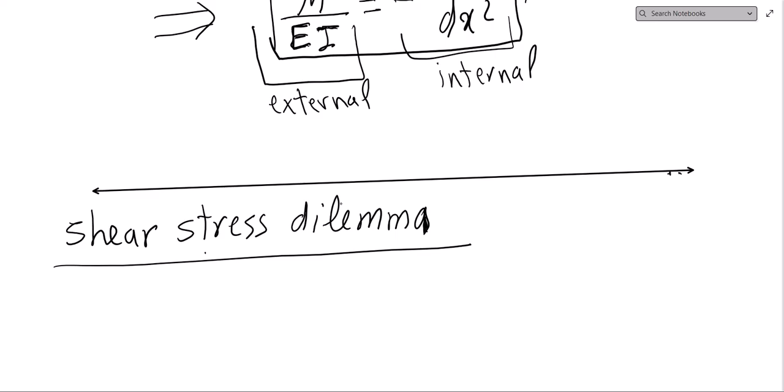When I say normal theory, I don't want to disrespect Euler beam theory, but because of the assumptions it simplifies a lot and it loses this connection. But in general, the 3D theory of elasticity or any further theories that we will discuss, like Timoshenko or Reddy and others, we will see that this connection is not lost.